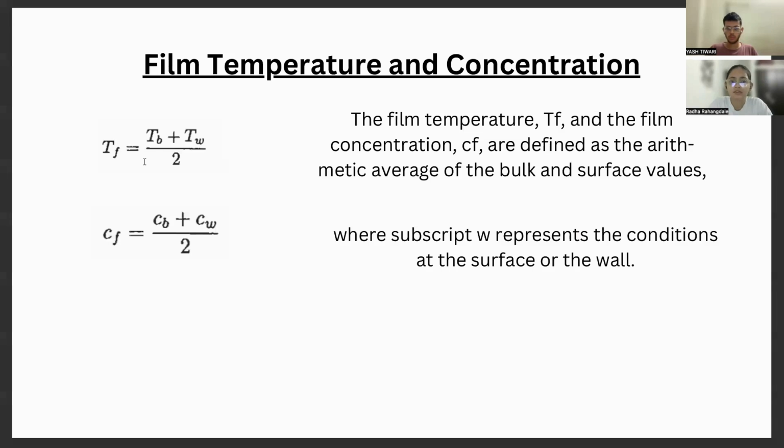Now we will see the film temperature and concentration. The film temperature, denoted by Tf, and the film concentration, denoted by Cf, are defined as the arithmetic average of the bulk and surface values. For example, Tf is equal to Tb plus Tw by 2, where Tb is the temperature of the bulk and Tw is the temperature at the wall.